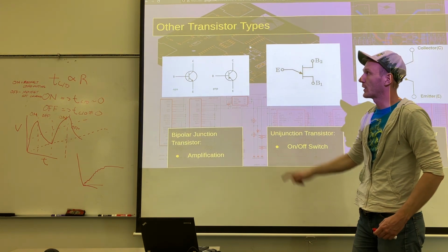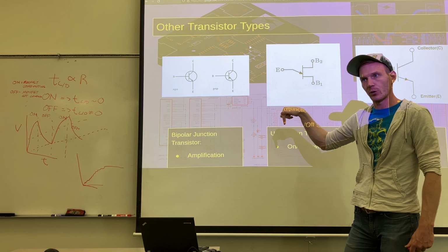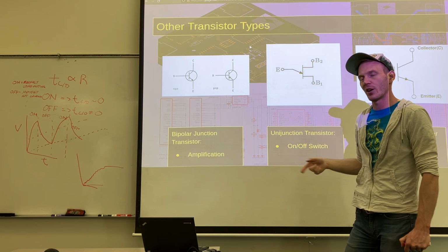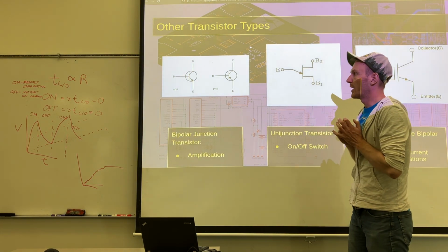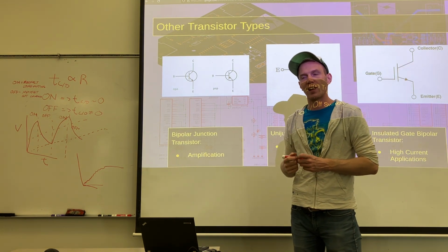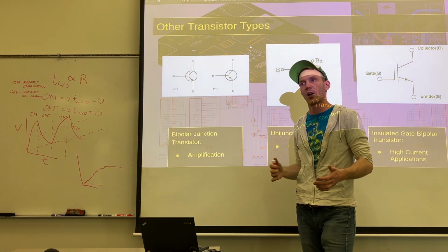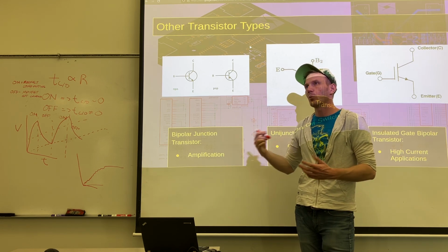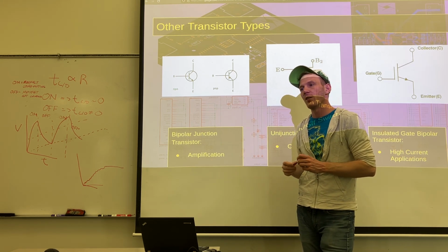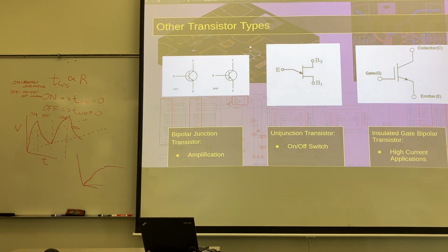That is important because bipolar junction transistors do care about which way flow is going. They are like diodes that you can turn on and off to some degree. But we mentioned earlier about gate valves with the MOSFETs, and that if all you have is a gate that just slides up and down, that's not actually good for throttling. These are more like throttle valves. So they have a very linear relationship, which is why they are used when MOSFETs are like 99% of everything. So I'm gonna erase this if nobody else uses it.